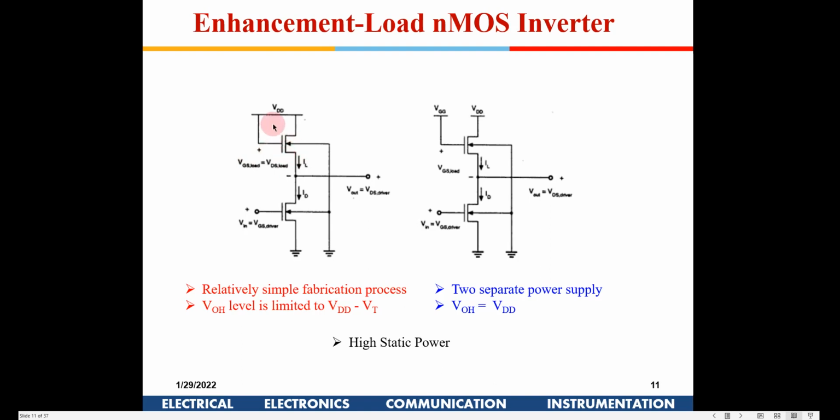Okay. So here you will find this NMOS. You are supplying VDD out here. So this is a kind of diode connected NMOS, you can call this. So obviously a diode VT will be dropped. So this is not a perfect transmission of one by an NMOS, we know. So the disadvantage was we had the total voltage not coming here, so noise margin got deteriorated, right, in this case.